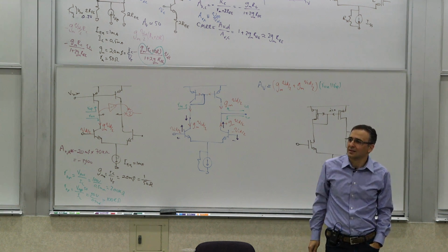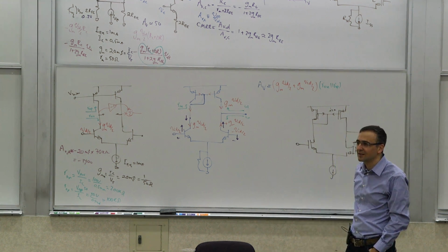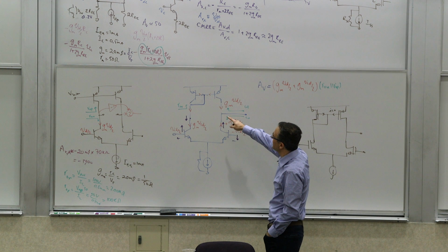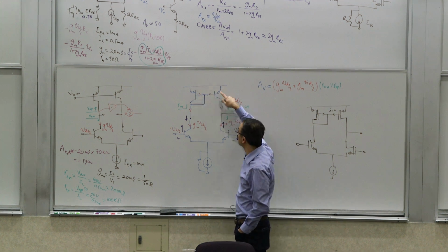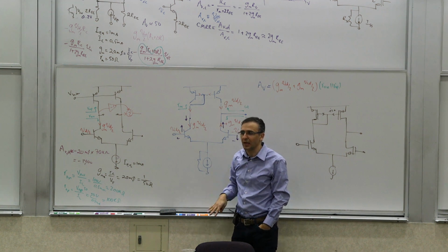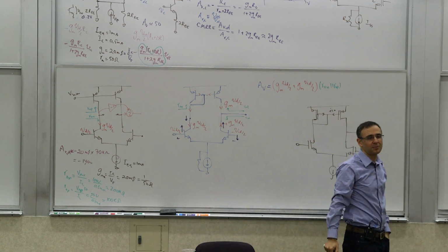Yes. When you have, like, an Early voltage, then your gains are probably slightly different, and then you get some differential to common mode conversion. Yeah, you have slightly different voltages, because this voltage is like one VBE, but this voltage is fluctuating a lot. So there's one aspect there. So there's some nonlinearity associated with that. That's true. Any other problems?